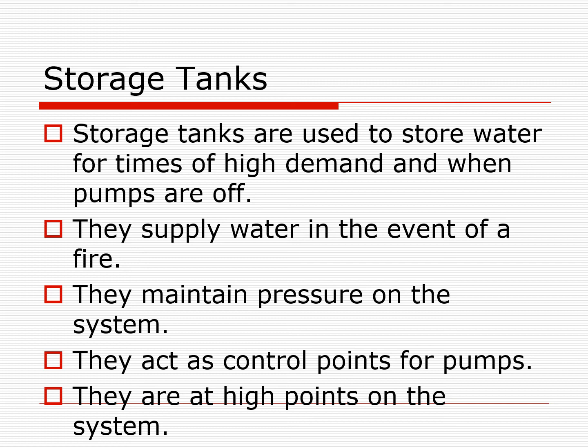Now, I mentioned to you that they supply pressure. Well, hydraulics tells us that our pressure in a system is based solely on the height of water that is above us. So when the pumps are off, the water pressure is based purely on how tall that tank is above where I'm measuring the pressure.